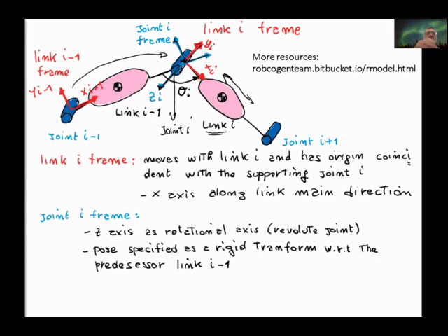So you need to think about a chain of transforms that goes from link, then to the joint, then apply the joint rotation, then again another rigid roto-translation to get the next joint and apply the joint again. And we can find all the frames along the structure for all the joints and links.